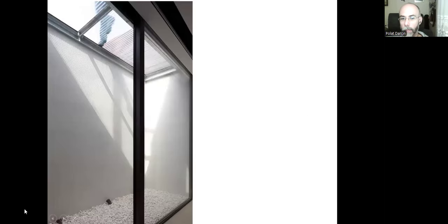And we can create an areaway as big as we want. Here, if we just need natural light, then we can close the upper surface with a semi-transparent material. We will have light, but we won't be able to get natural air this time.